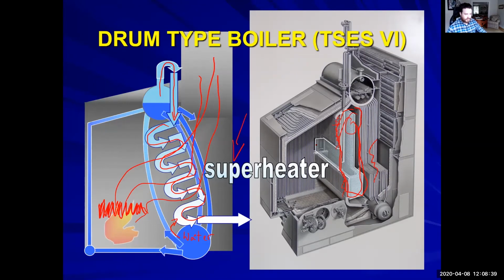It has to do with the state of the water that's in there. Generating tubes insulate the heat inside the superheater. So you're insulating, you're protecting your superheater. Okay? You are trying to actively keep your superheater tubes from basically burning up, because you're always going to have water, always going to have a liquid in your generating tubes. All right, so we're just protecting our superheater by doing this.